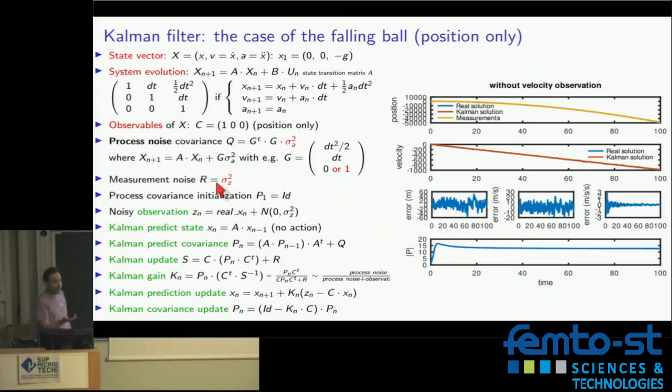But the point of Kalman filtering is to compare how a model evolved with respect to noisy measurement. Kalman tries to optimize the weighting of the contribution of the model with respect to the observation. So Kalman will say, okay, my model is very poor, my observation is much better, so let's forget about the model. But if the model is converging better and the noisy measurement is degrading the observation, Kalman will say, I will rely more on the model than on the observation.